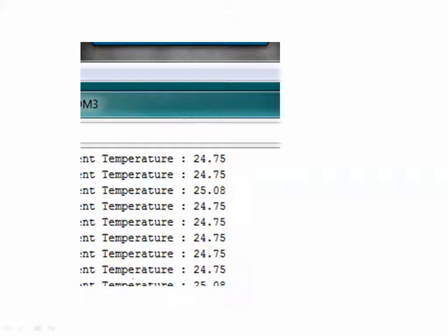Similarly, we can have other sensors also, but the procedure or the connection will remain the same. You will get the value and assign it to a variable, multiplied by what is known as the reference value. That reference value we can get from the sensor manuals. You multiply by that reference value to get the actual voltage relationship.